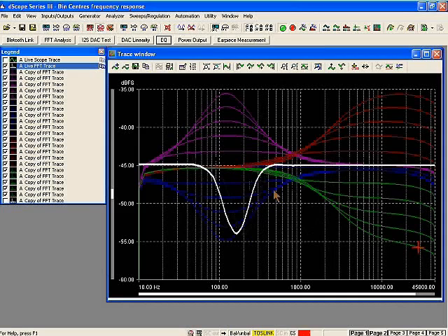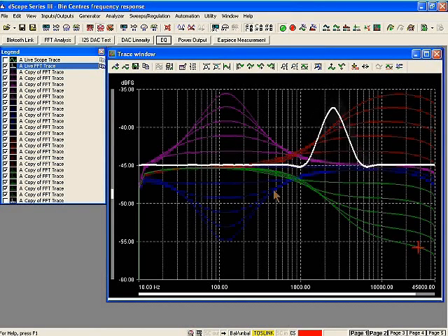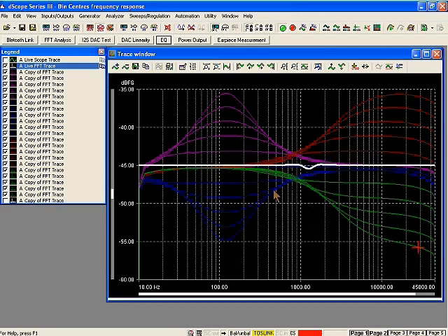We can see that we're obtaining a very large number of different frequency response measurements in a very short space of time. So if we have a large number of DSP settings that our Bluetooth headset can potentially support, whether that's user adjustable or whether that's controlled within the firmware, it doesn't matter. We can adjust these different parameters and make measurements very quickly, and this is a really powerful way of measuring frequency response, and this is really why I wanted to concentrate on this particular methodology for accomplishing this measurement.